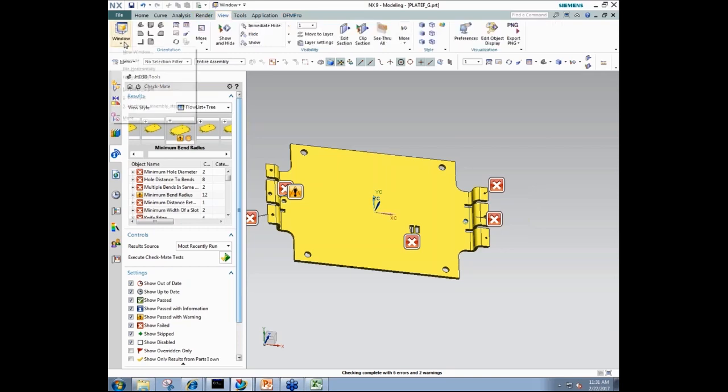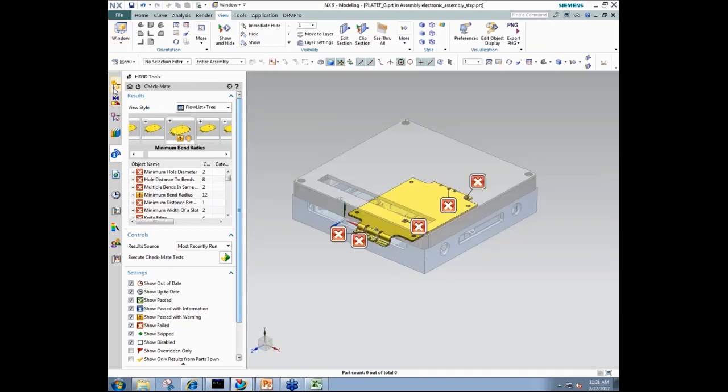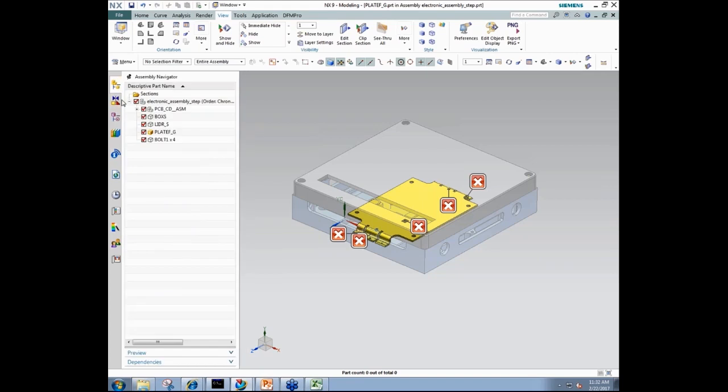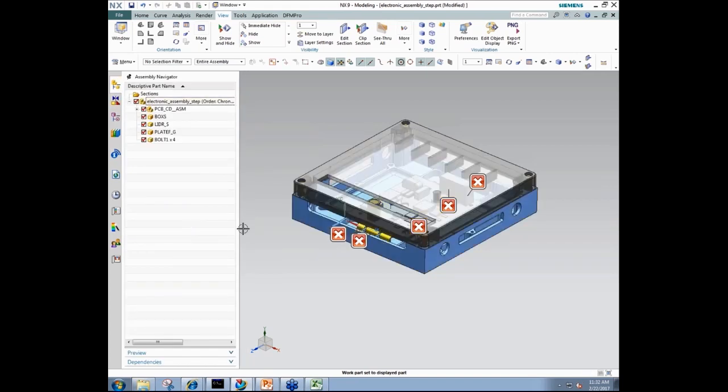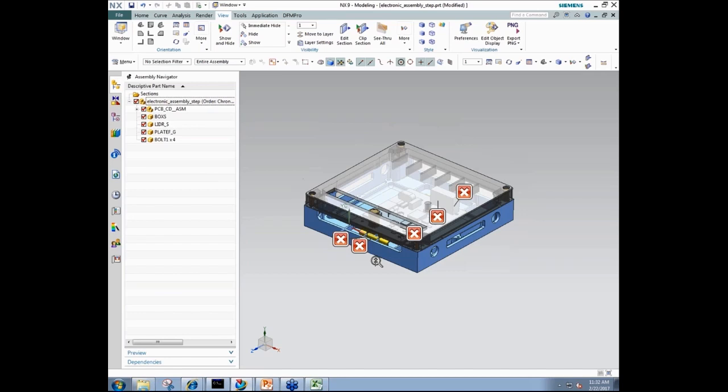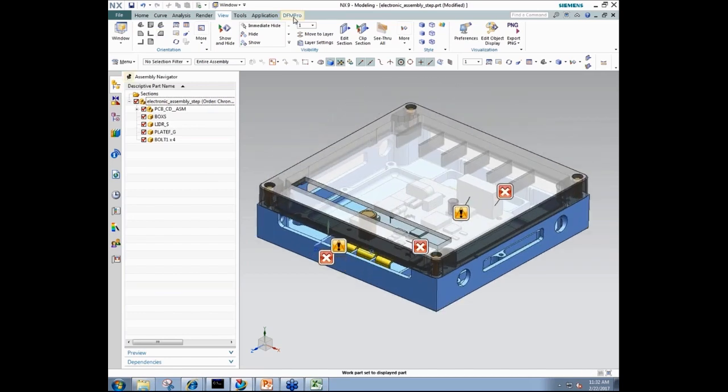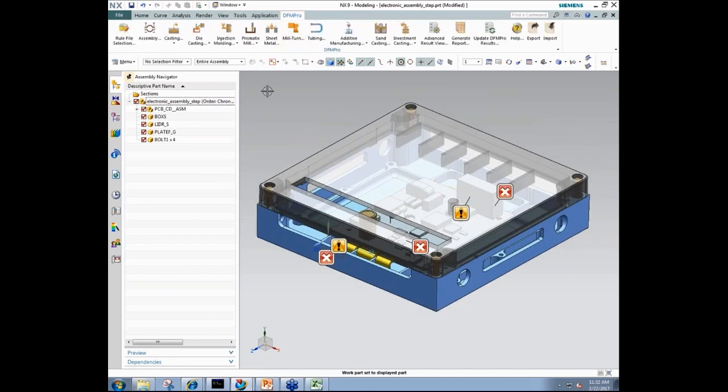And just very quickly going on to the assembly. So finally, at a piece part level, every piece part is taken care of for the DFM requirements. Now finally it has to get together and assemble. So there is also this assembly module which we have in DFMPro, which looks at whether my parts will go together well, whether I have all these bolted joints, whether they have sufficient engagement, and the right hole clearances, all of that. So it will check for those.